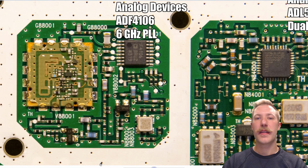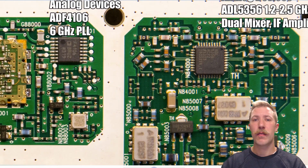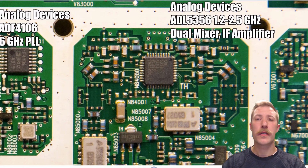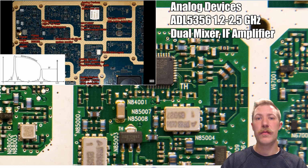Now I did mention that this was the heart of the amplifier. This is the PLL, which is an up to 6 GHz clock generating circuit. So all we do here is generate a very high speed clock, which is used as the intermediate frequency in the down and up conversion mixers that I also showed earlier on the first receive part with the ADC. I also did another video where I looked in detail into down and up conversion, so if you like that topic, check out the description.